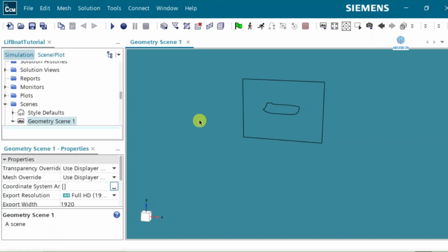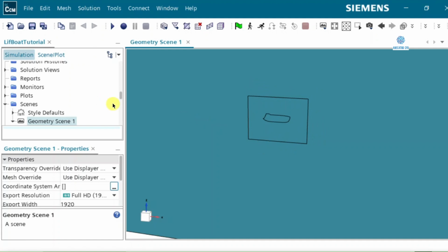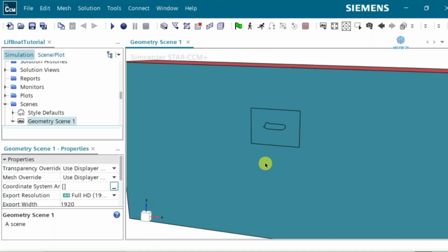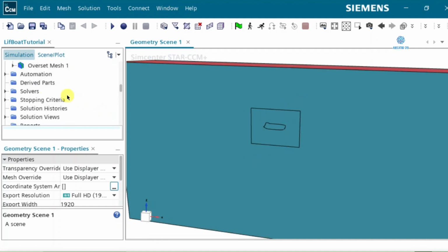In the previous examples, we saw that multi-stage meshing needs refinement boxes. Inside those refinement boxes, we apply volume or surface controls. That is how we guide the mesh and generate better cells. So here I need to create several blocks for that purpose.